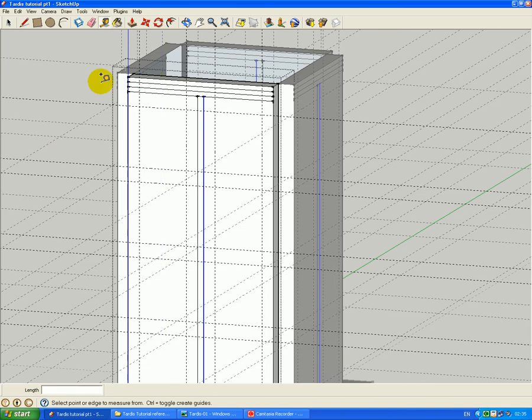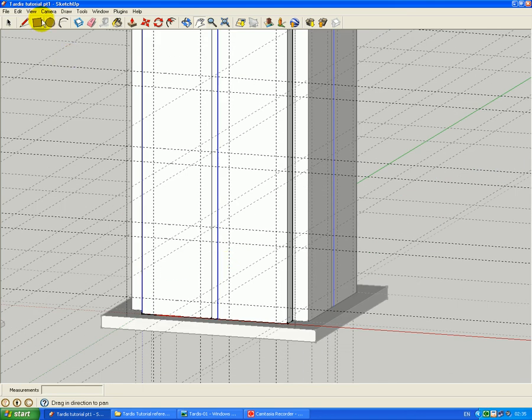Right. I'm going to create the first recessed panel. So we're going to go to our box tool. It'll snap to the intersection of the two guidelines, and again snap to the intersection of that guideline. Select that polygon, or that box we've just made, and we need to do an offset on that. Offset by 10.